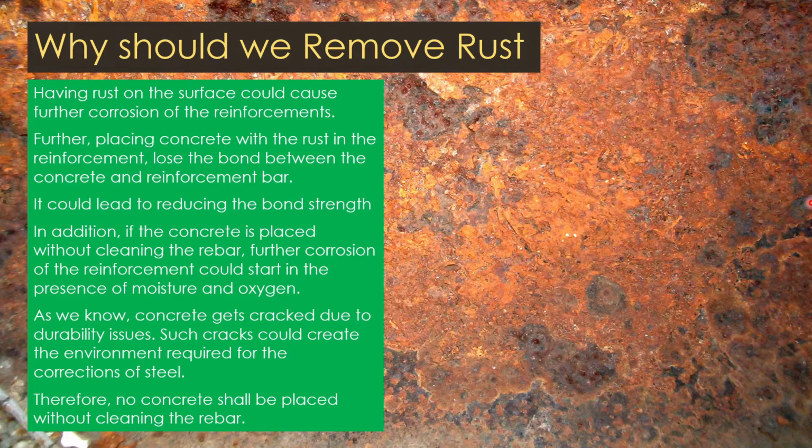As you know, concrete gets cracked due to durability issues. If rusty reinforcement, or reinforcement that has initiated corrosion, is within the concrete, then with those cracks the corrosion will speed up and continue further and further. Then there will be issues for the structure.